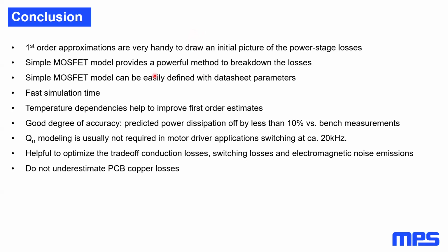For those of you who are familiar with electrical simulators such as QSpice, we showed a simple test bench to accurately estimate and break down the MOSFET losses with an even better degree of accuracy. This method is quite helpful to find a reasonable trade-off between motor driver power dissipation and EMC compliance. Finally, the largest source of inaccuracy we could identify between first-order estimation and/or simulations is the MOSFET RDS(on) junction temperature dependency. As the device is heating up, its channel resistance is increasing, thereby pushing the losses further up.